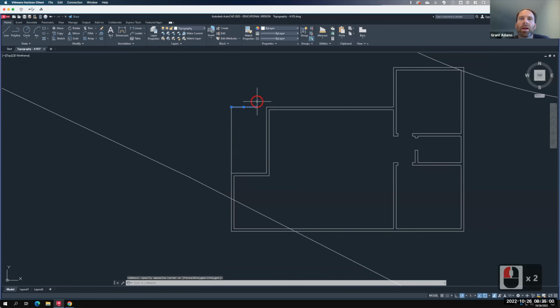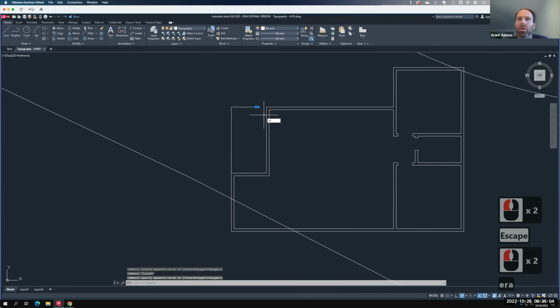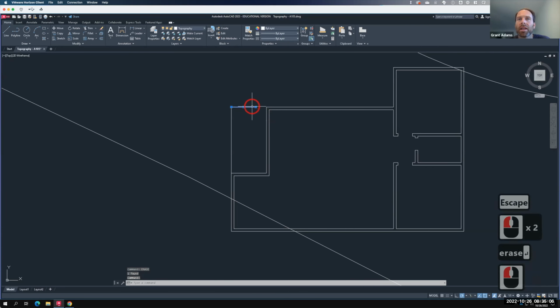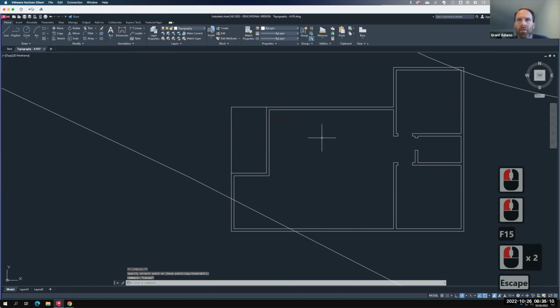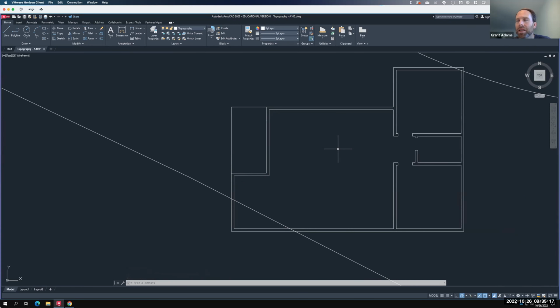We'll talk about how you bring in blocks and use block references, etc., to accentuate your floor plan and give yourself a little bit more detail. So it's not a requirement right now to add furniture in. You could draw kitchen cabinets if you wanted to. You can mass out things and think about how big they are. I would be thinking your bedrooms should be somewhere in the neighborhood of 12 feet by 12 feet. That feels about right. Your bathroom, absolute minimum size would be 5 feet by 8 feet. It would be nice to be larger than that.